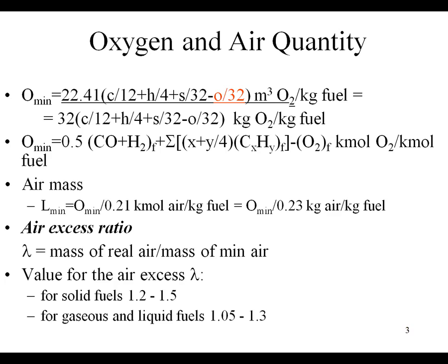The disadvantage of this air excess ratio is that with the oxygen, which has a positive role, you are introducing also nitrogen. So the values for the air excess ratio cannot be 10 or 11 or 2 or 3, because this would mean a lot of nitrogen carried through all the combustion facility with no use. Supplementary, you need more space. The pipes must be larger. Everything is much more complicated. Not mentioning the fact that nitrogen from the air, in special conditions, but this is not the object of what you have to learn.